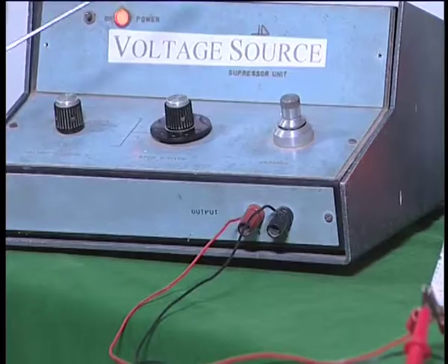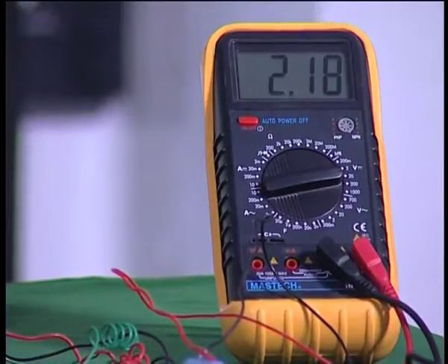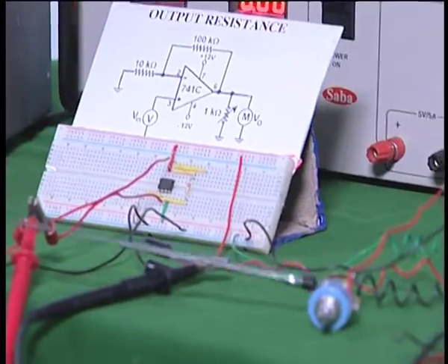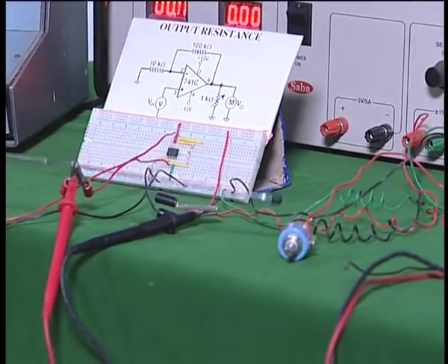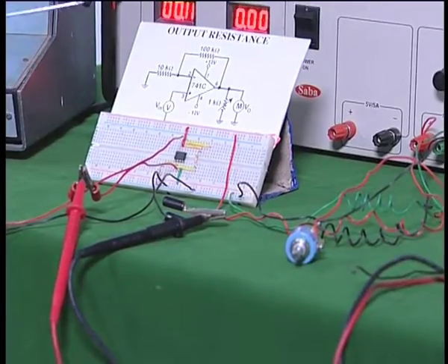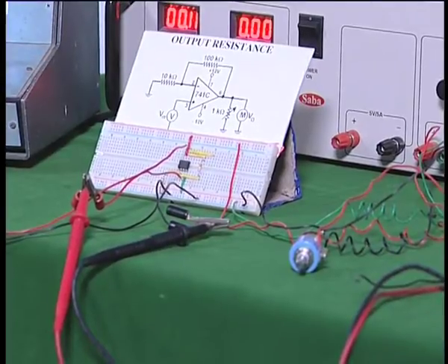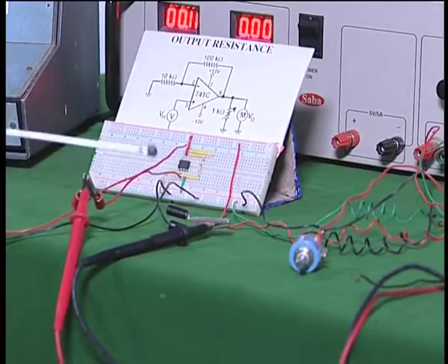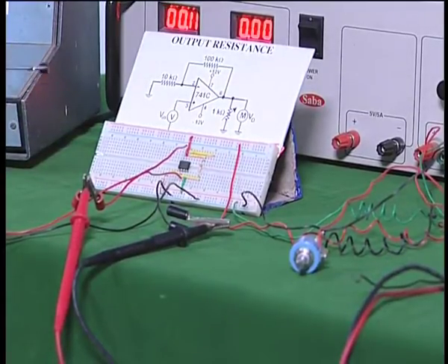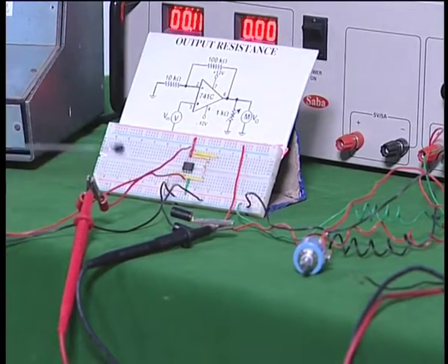Now, without disturbing any of the voltages, I should now connect the variable resistor, which is here. It is actually a 10 turn potentiometer. In our normal potentiometers, if you rotate by nearly 360 degrees, all the resistance variation would have been made. In this case, you have to rotate the spindle 10 times to make the variation possible for the whole range, and therefore, you can do it in much smaller increments of resistance. That is why I am using it.